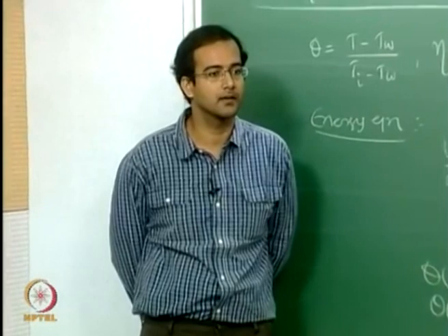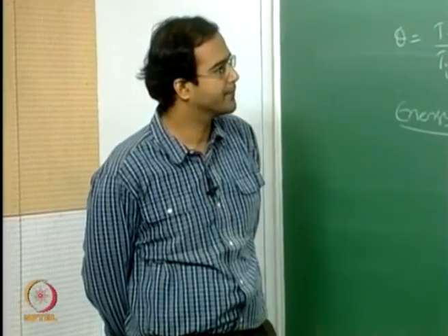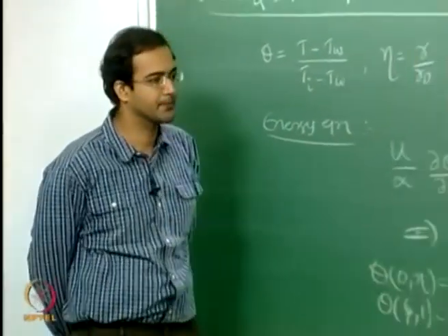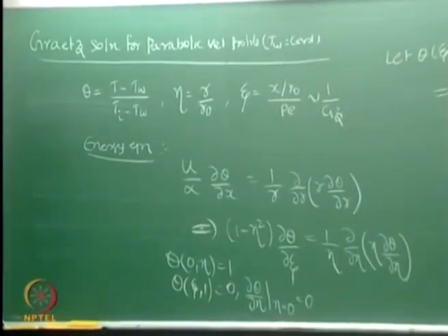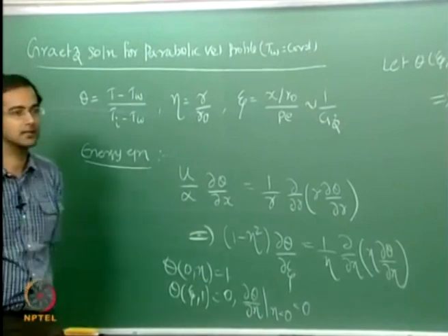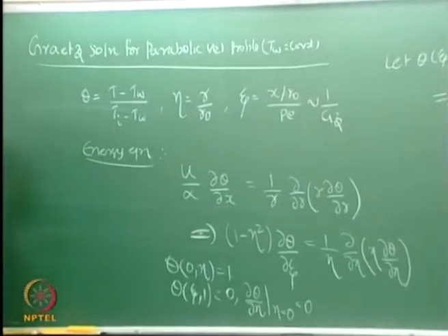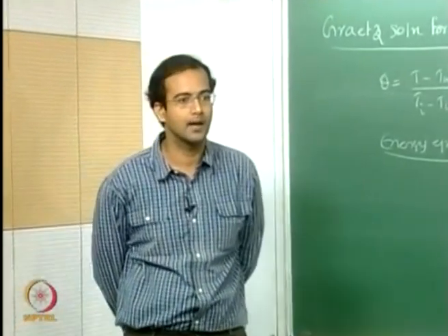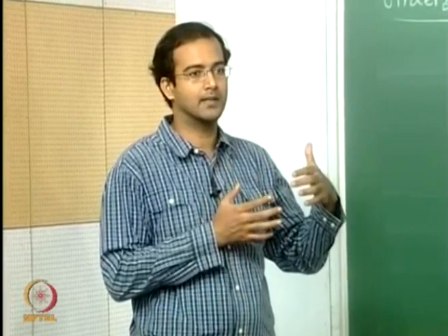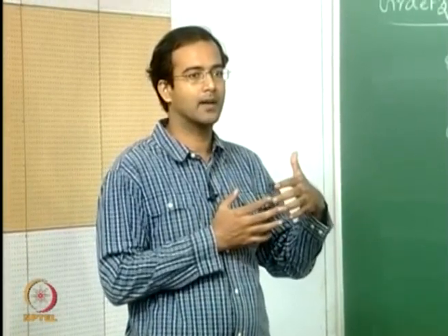So, good morning all of you. Today we will look at, in fact, a continuation of the last class, which was extending the Graetz solution. The Graetz solution was originally proposed by Graetz for slug flow profile, and it looks at the thermally developing region or the thermal entry region, wherein you are hydrodynamically fully developed and you are looking at only the entrance region where the thermal boundary layer is developing.